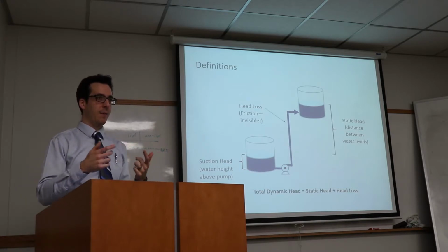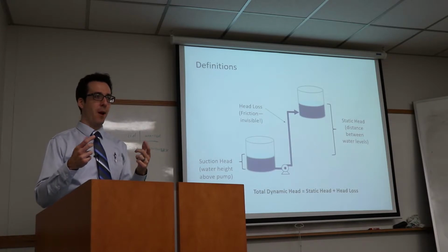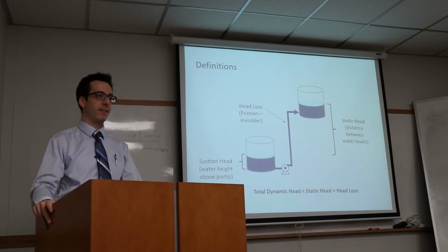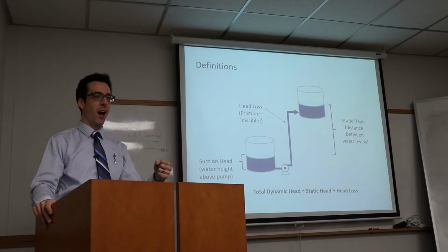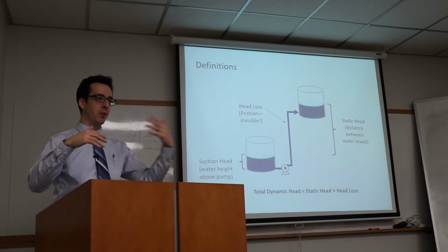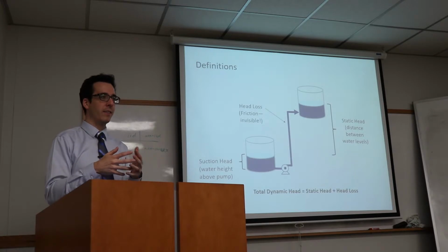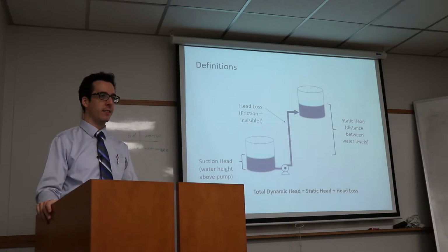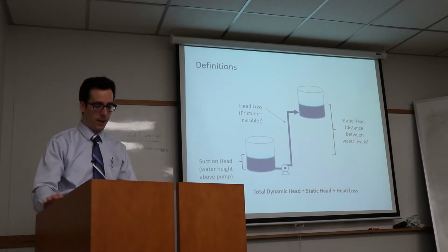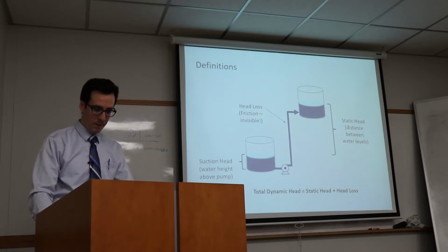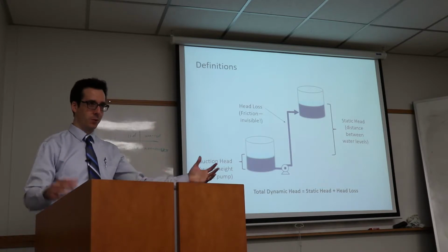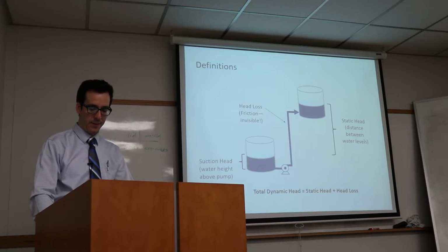So the total dynamic head is the head that the pump feels when it's running. Okay, not when it's stopped, not when the water's at rest, but when the fluid is moving, when the pump is running, what does the pump feel? That's the question you need to answer, and that's what we call the TDH, total dynamic head. I know this is all technical, and we'll bring it all together with some practice in a bit.